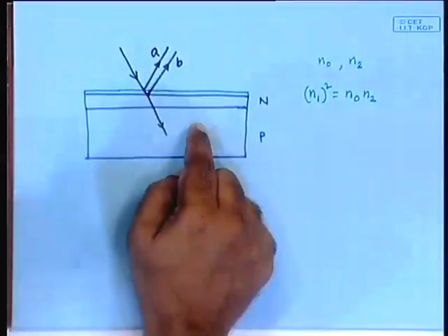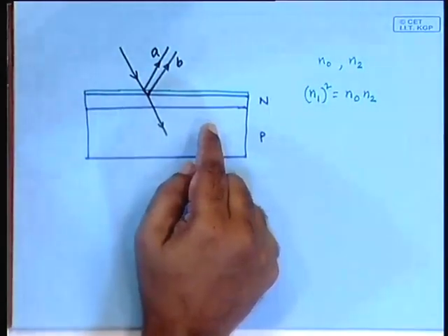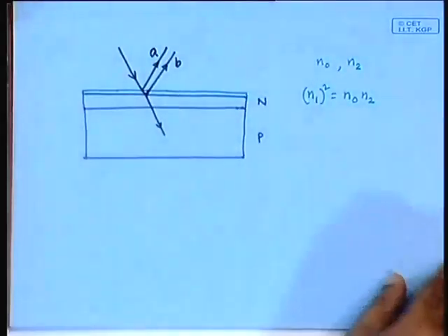So, this is how the anti-reflective coatings are used in order to increase the efficiency, and this is another thing that goes down, that degrades. If you look at old photovoltaic cells, you see the coloring is different than the new ones. The new ones have a different type of texture coloring, that is mainly contributed not by the silicon, but by the anti-reflective coating, and that is another thing that degrades over the years as time progresses. Okay, so you have understood the idea of the anti-reflective coating.